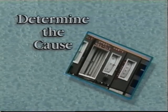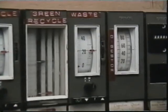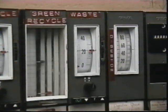When the necessary preventive measures are completed, the next step is to figure out the cause of the problem. We indicated earlier that a high blanket level in a secondary clarifier can be caused by improper recycling or wasting of the activated sludge. But these variables were found to be normal, which eliminates this possibility.